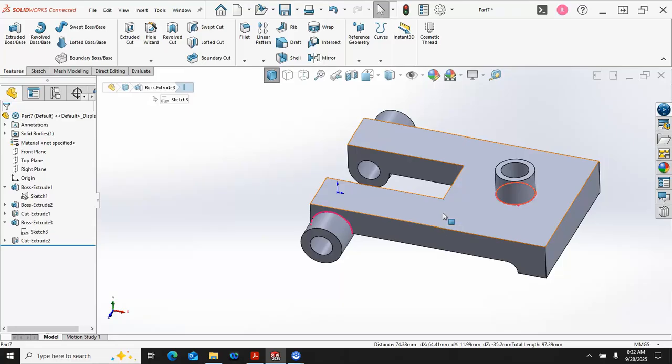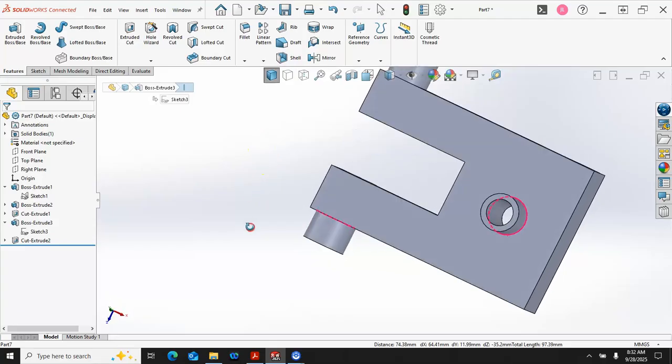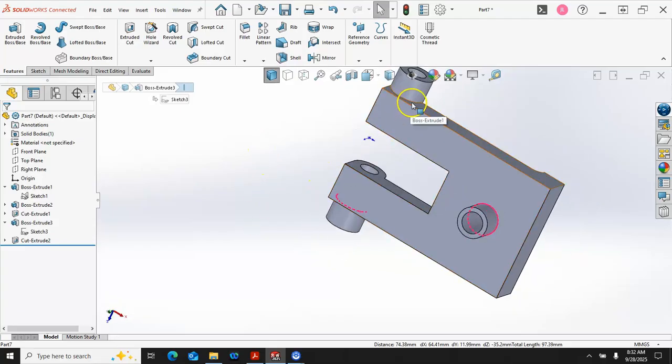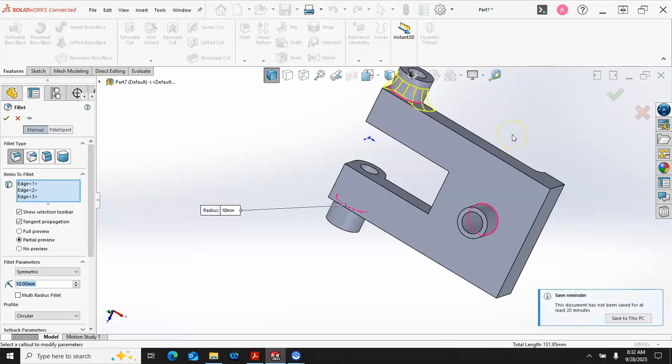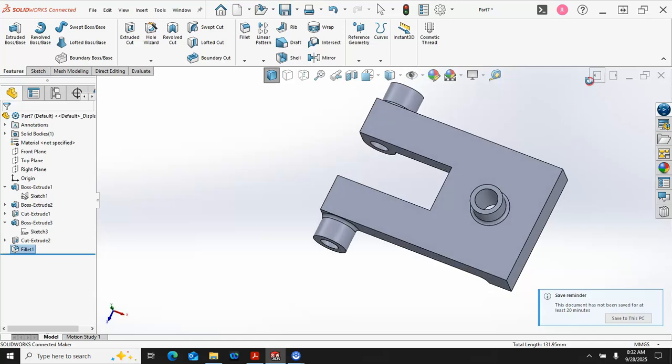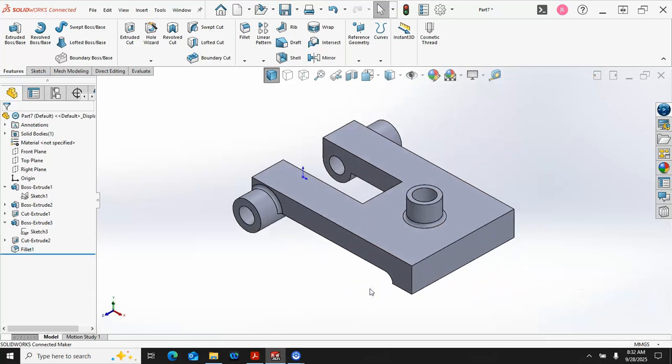All right, so our radiuses then, I believe they said typical, so let's see, where did 3 times radius of 2, so nope, not the whole face. Make sure I'm getting just the edge. We go into the fillet, box is highlighted so I can type in the 2, and we'll go ahead and accept. All right, that looks pretty good.